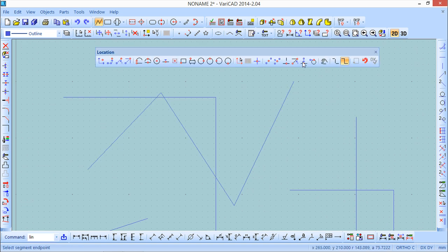Then if I try to draw something, let us grab, for example, a grid point near here, and you see now that my mouse is jumping from point to point because I have the grid at 5 millimeters and also 5 in this increment mode.